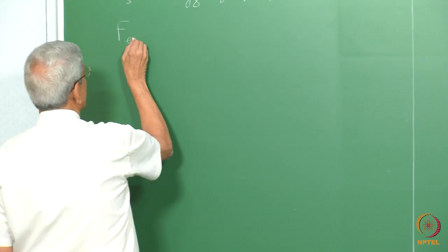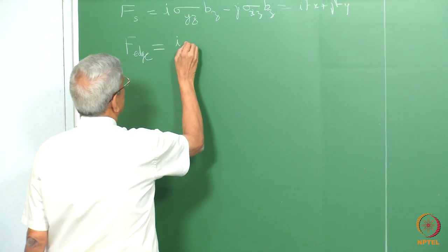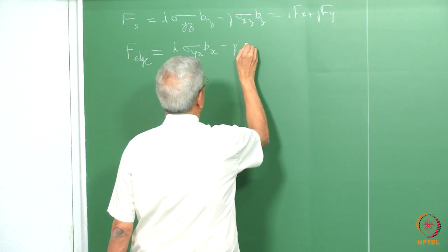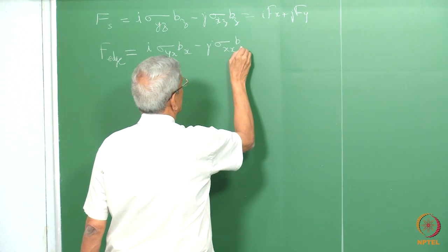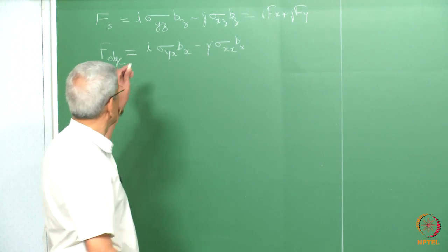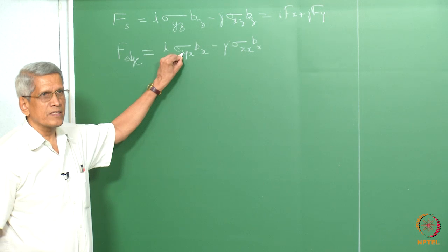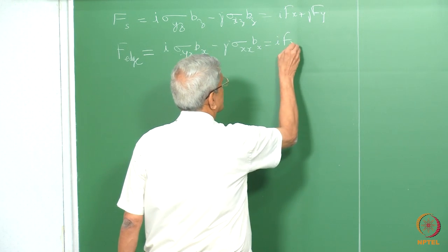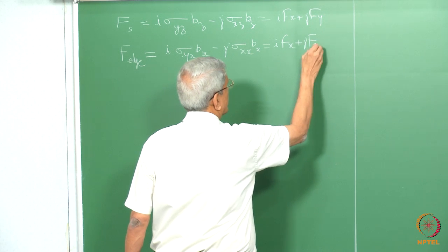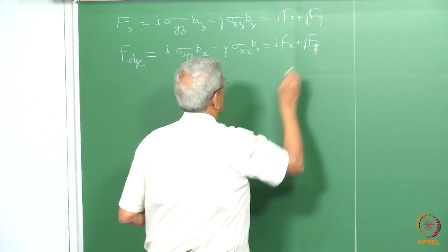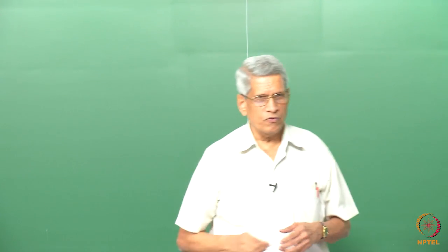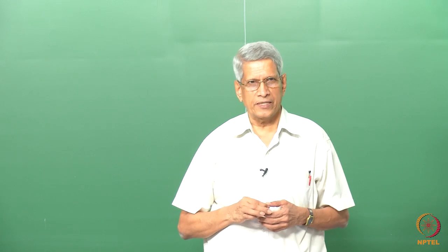Whereas when we derived an expression for the force acting on an edge dislocation, the application of the shear stress develops a component of force i Fx, that's the force in the x direction, whereas the tensile stress being applied to the material generates a force essentially in the y direction, correct?